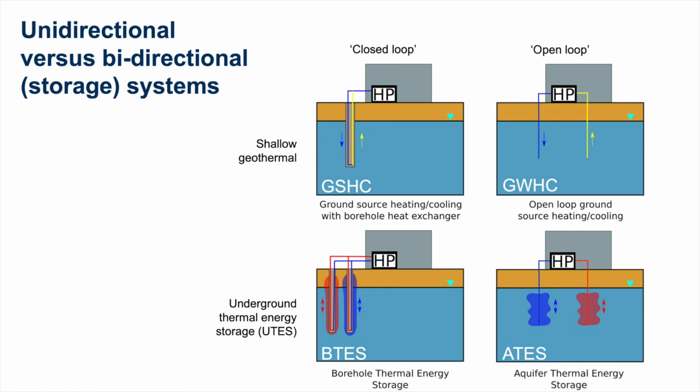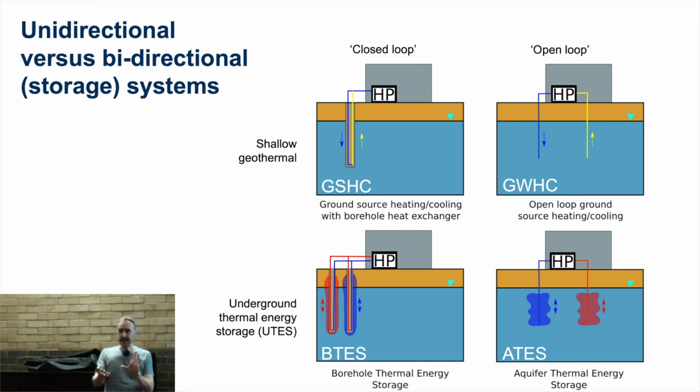Okay, so that's the basic principle. For shallow geothermal, we bring this relatively low temperature fluid out of the ground, groundwater if it's open loop. We then take its heat or cool out using a heat pump, and then we pass the waste back into the aquifer. So the best we do is that we produce water at the ambient aquifer temperature. But what would be neater? Okay, so I said that in the summer, we're going to be injecting waste heat back into the aquifer, and in the winter, we're going to be injecting waste cool back into the aquifer.